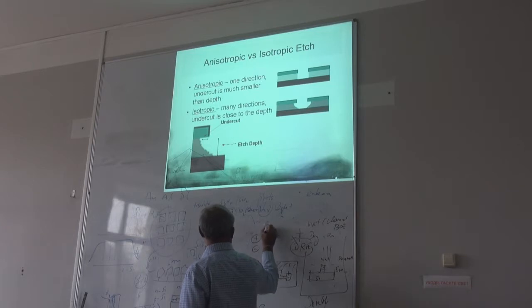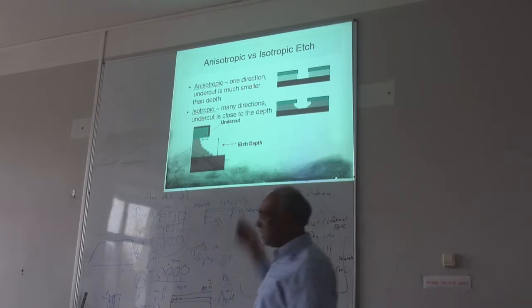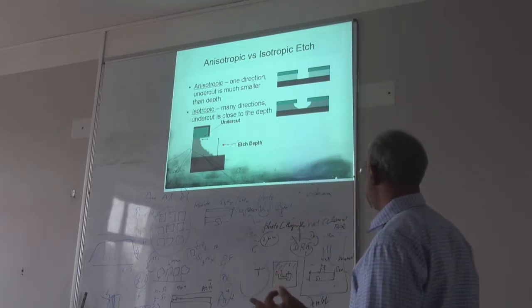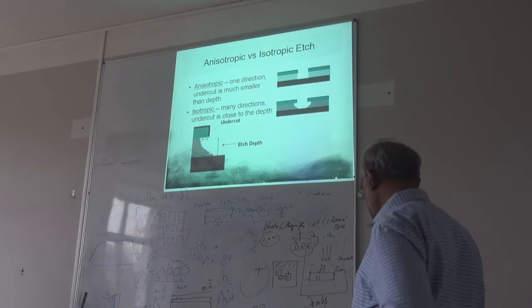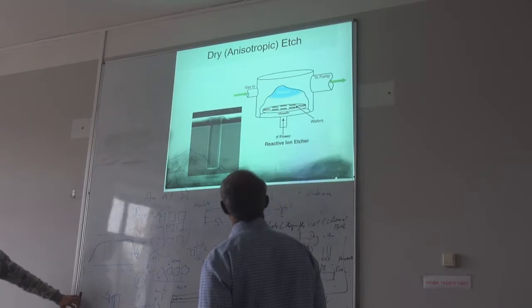Then finally, maybe I will talk about these features we were talking about in photolithography. They are micrometers, right? Can be 2 micrometers or even less than that. But if you want to use nanometer scale, instead of using light, we can use electrons, right? Electrons, like I said, have the de Broglie wavelength, which is in the nanometer scale. You can use much finer features.